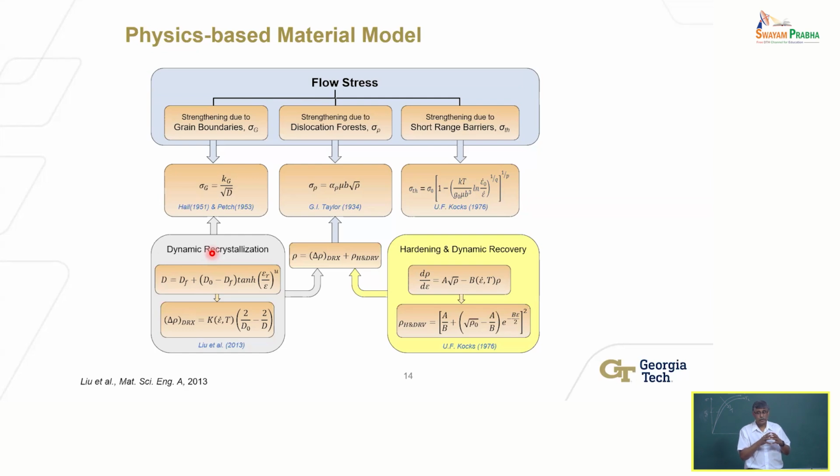Then new grains may form, called recrystallization, where fresh, approximately equiaxed grains form. They're not the deformed grains anymore. The deformed grains get replaced by equiaxed grains. And then if you continue to apply more heat, those newly recrystallized grains will grow.